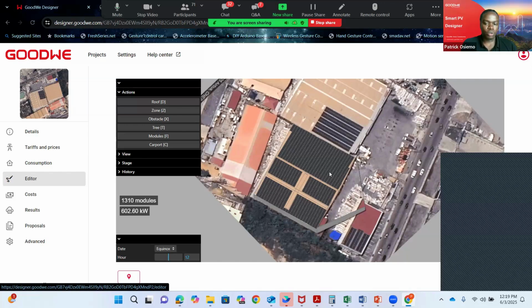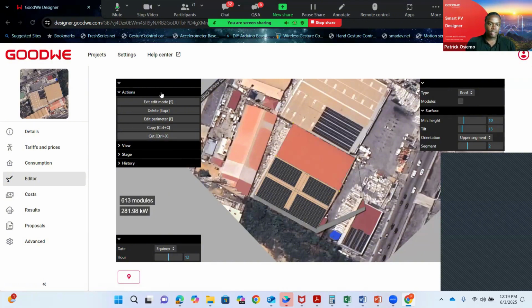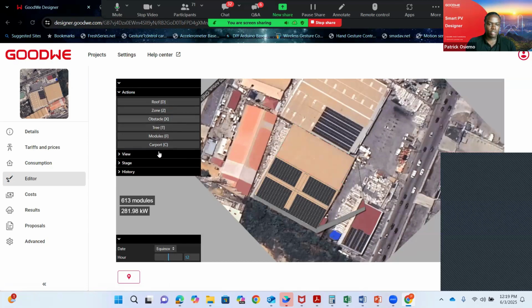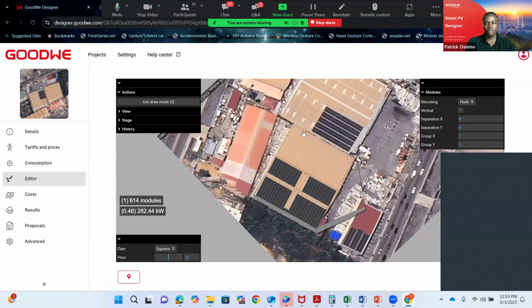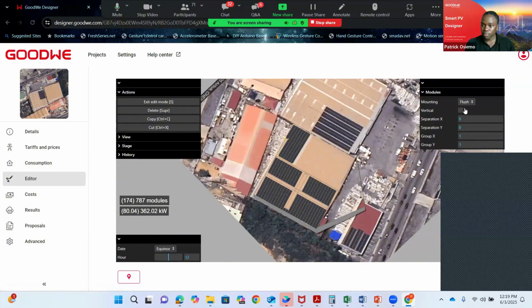Yeah. So if you'd like to do that, there is a manual way of laying out the panels. So basically, let me just highlight it. If I uncheck the modules part, then exit, I can select modules. Then I go there, click, drag, finish that, escape. Then I select this, I do tilted, choose different segment.